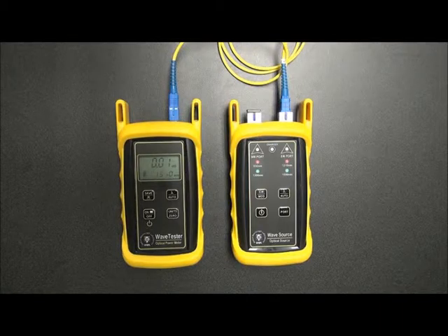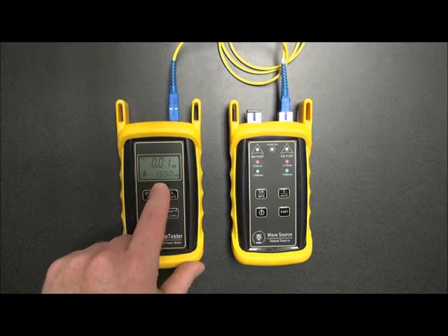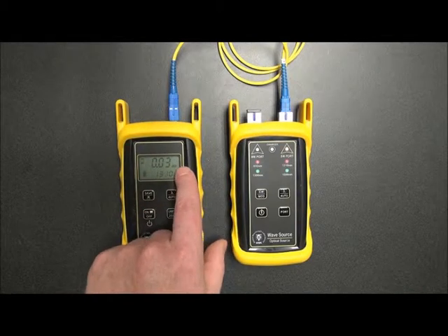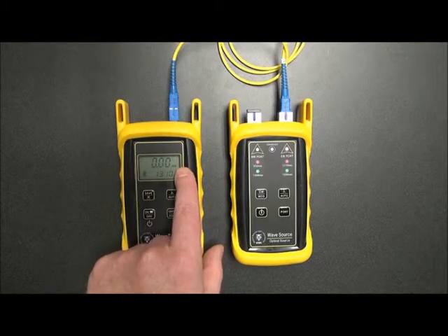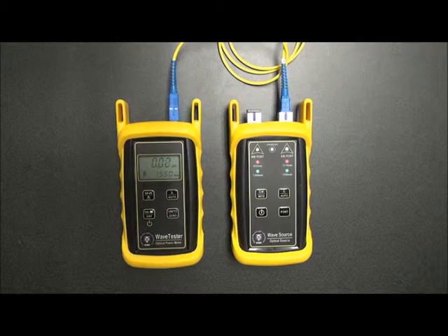Okay, now you can see that for both wavelengths, we're reading very close to -0 or 0.00, which means that we've zeroed out our equipment. You'll also notice that the units indicator switched to dB. dB is loss mode. That's what you're using to actually measure the loss of your cable. So now that we've zeroed out our equipment and made sure that our patch cables and testers are good to use, it's time to take the units to opposite ends of the link and start our optical loss measurements.